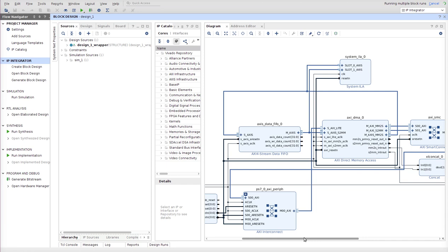With no operating system, we're going to be using the SDK and the examples that Xilinx made available to you. So basically you have a series of DMA transfers that can be done using interrupts, or you can use polling. You can transfer different sizes of data. Yeah, so it's actually very easy.